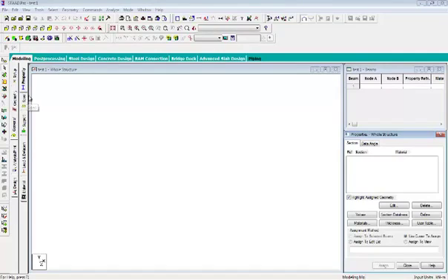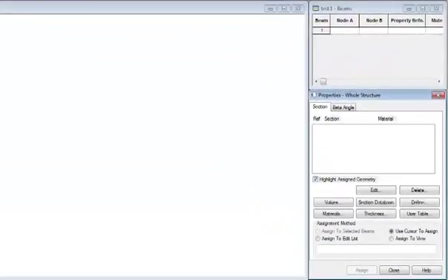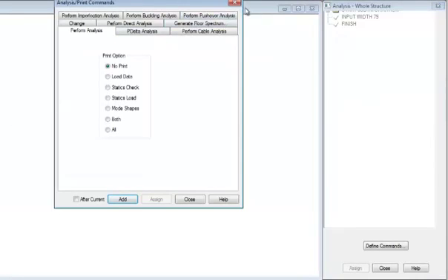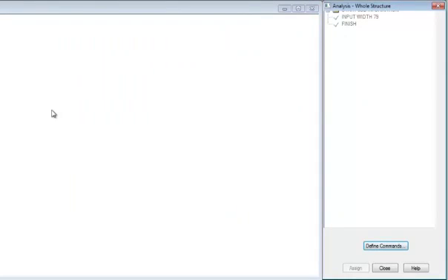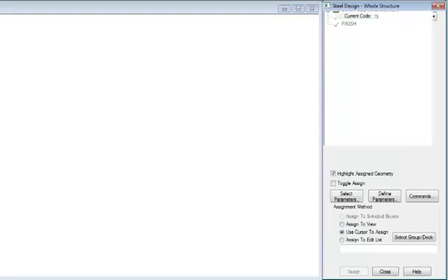These are various things like properties, specifications, supports, the properties of the material that we are going to use, the dimensions, and all. Then the analysis will be done for the structure, the bending moment, the shear force, everything. And then the design, on the basis of the bending moment, shear force, BMD, SFD and all, will give us a particular design. Fine.